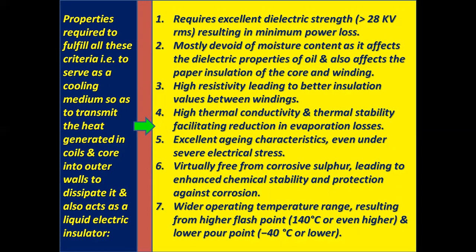Number 2, mostly devoid of moisture content, as it affects the dielectric properties of oil and also affects the paper insulation of the core and winding.